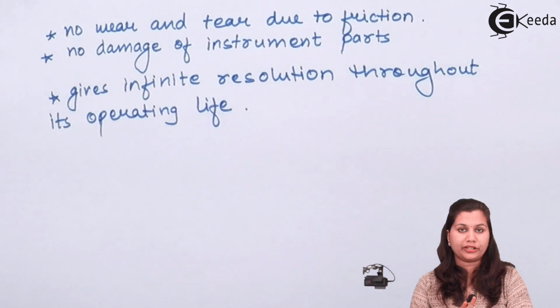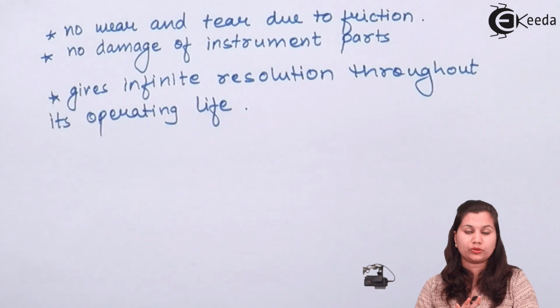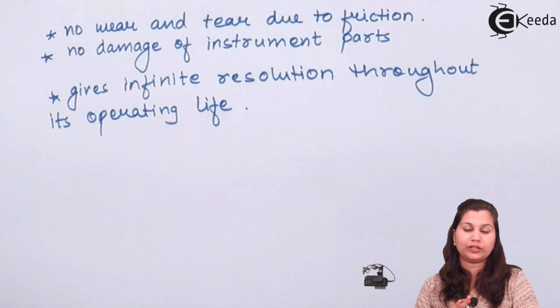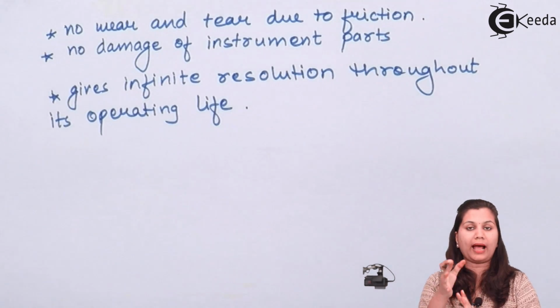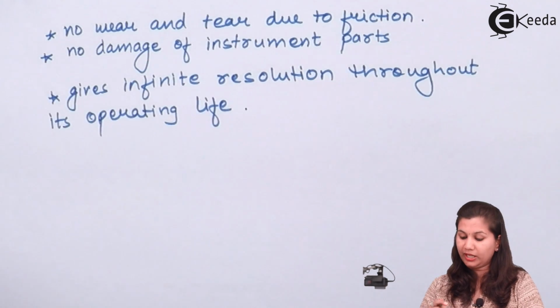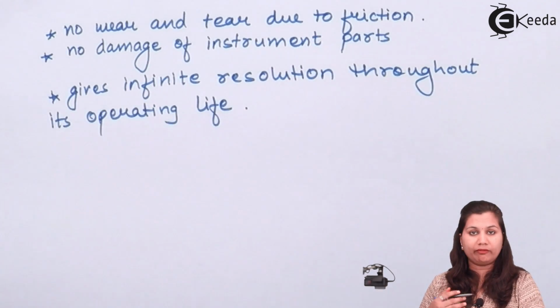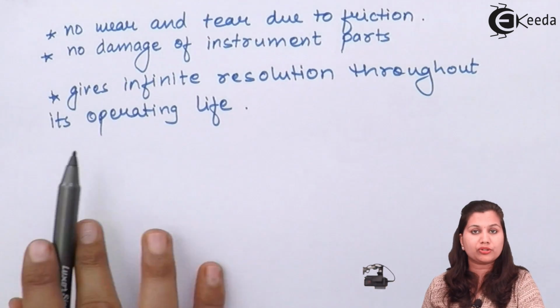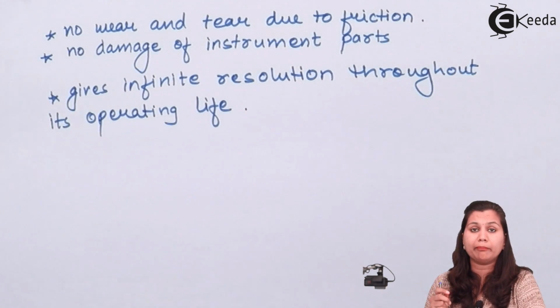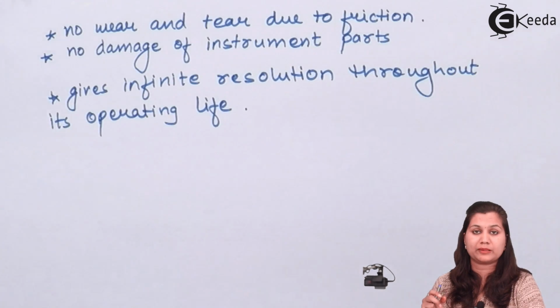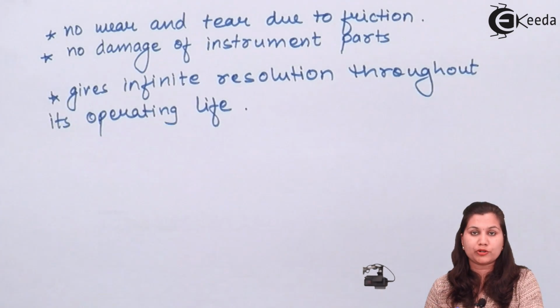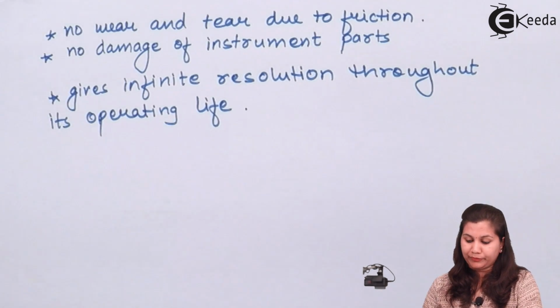So as no friction is produced, and also there is electrical isolation between the core and the coils of the LVDT, this gives the LVDT an infinite resolution property throughout its operating life. Means very minute changes in the displacement can be accurately measured by the LVDT.